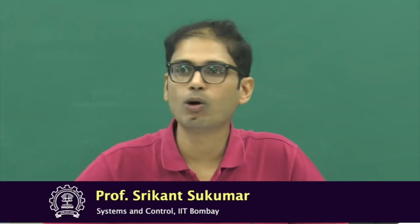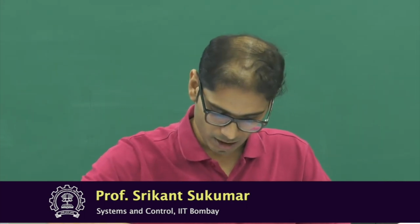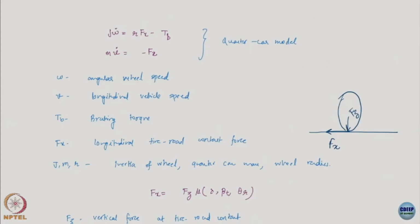So we were looking at these models. There are a couple more models that we will look at. This is the anti-lock braking system model. Again, a very mechanical system model. Here you look at the car as a quarter car, what's called a quarter car model. These are all very standard terminology in automobile systems. You use the quarter car model to do a lot of design, suspension, braking. You can do a lot of design with just the quarter car models, and you expect them to work well in the real system also.